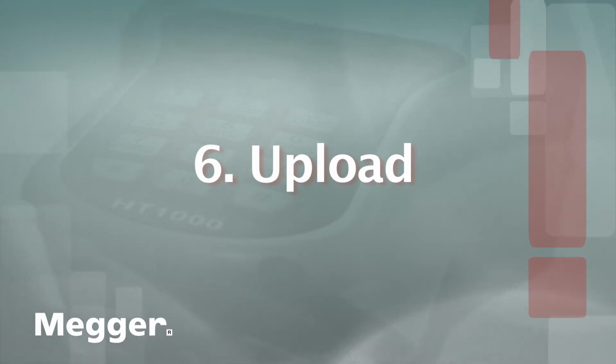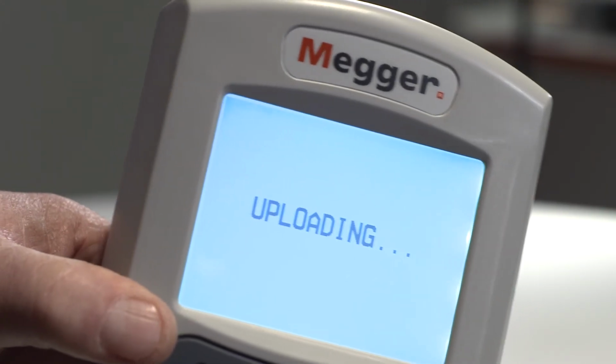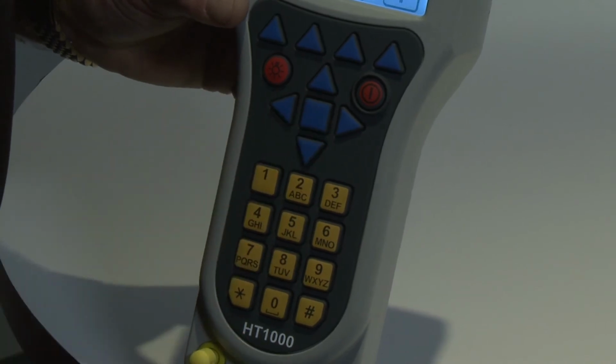6. Upload is used in conjunction with a PC and USB cable. Saved TDR test results can be uploaded for analysis and used in a customer-driven database. The software must first be loaded from the provided CD and set up on the PC. See the HT1000/2 user guide for information on how to install and set up the TDR uploader software. To return to the main menu, press the Enter Return Home key.